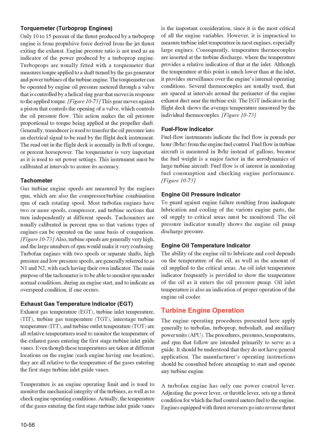Engine oil temperature indicator. The ability of the engine oil to lubricate and cool depends on the temperature of the oil, as well as the amount of oil supplied to the critical areas. An oil inlet temperature indicator frequently is provided to show the temperature of the oil as it enters the oil pressure pump. Oil inlet temperature is also an indication of proper operation of the engine oil cooler.